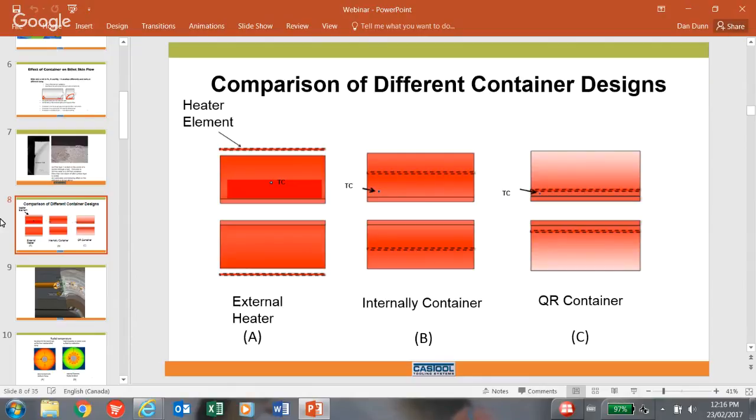It's a fact that mechanical stresses within the container and liner assembly are increased on both the liner and body with the placement of air cooling grooves. Also, the heat transfer from the liner and body is greatly reduced as the surface contact area has been compromised, which contributes to the increase of liner temperatures.